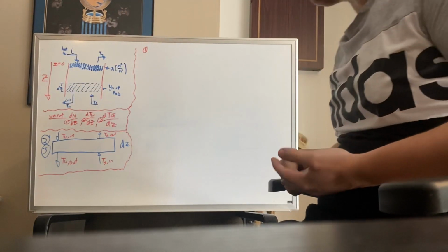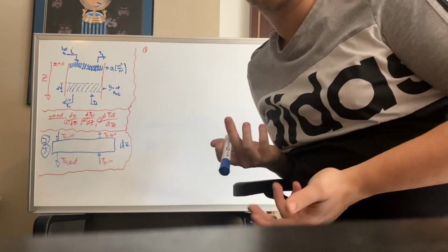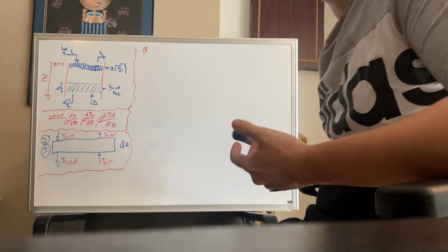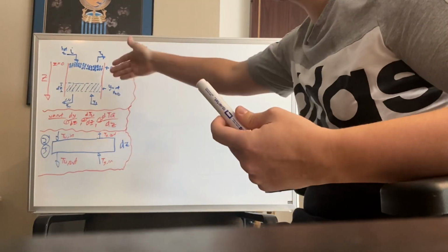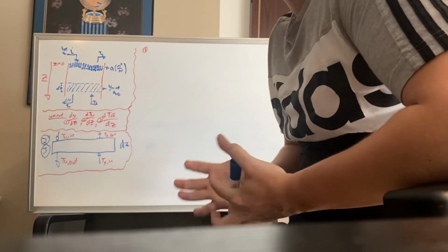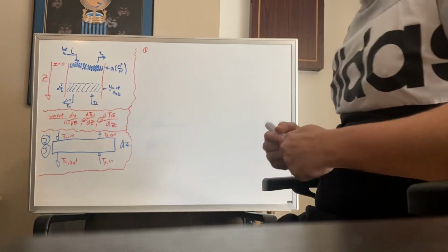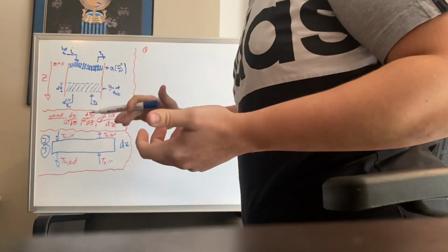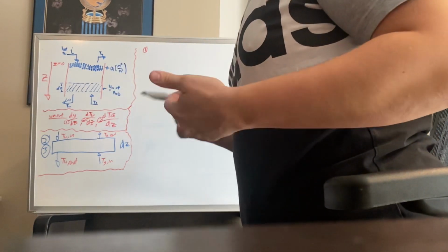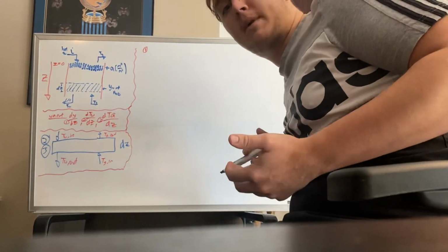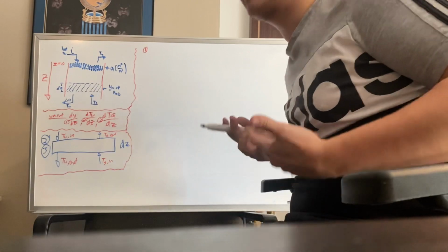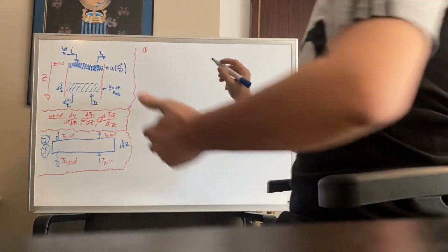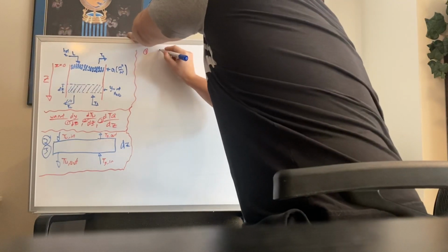The first part we're going to want to look at is probably the rate of change of the mole fraction of water with respect to the change in distance in the cooling tower. The first thing we know is that because liquid is flowing in and cooling down, and gas is going up, we will be losing some energy and some mass of this water to evaporation and heat change.